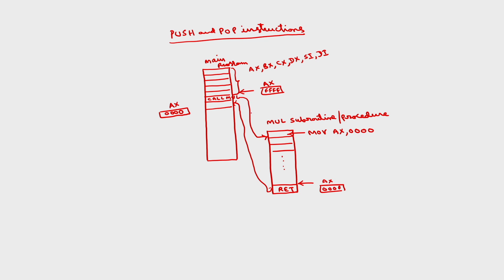Before calling this subroutine, you store the contents of all the registers, regardless of whether these registers have been used in the subroutine or not. You just push these onto the stack. This operation is called the push operation. Push these contents onto the stack. Stack is a set of memory locations again.